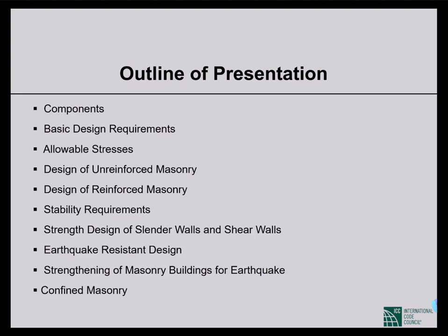For gravity load, we go for the tributary approach, like the load coming onto the slab. Half the span on each side of a wall will be carried by the wall as gravity load. For wind load also, we go by the tributary approach: on each side, half of the span of the lateral wind load coming onto the structure will be carried by the wall. So in that case, the external walls will carry half of the load.